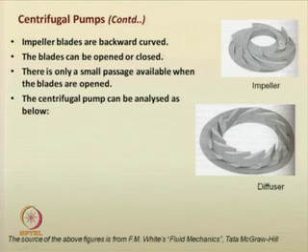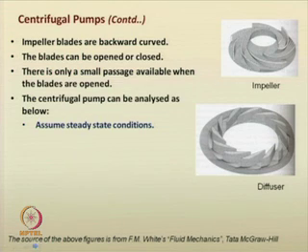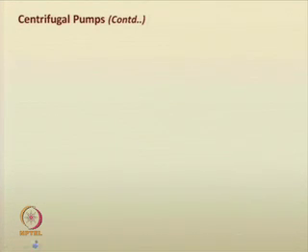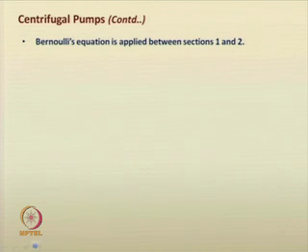Now for the centrifugal pump, we usually analyze it with the following assumptions. We first suggest steady state conditions; the entire system is in steady state condition. Then we neglect the effects of viscosity and we neglect the heat transfer mechanism. Then we apply Bernoulli's equation between sections 1 and 2. Again, I am just redrawing the portion. You have the inlet here.